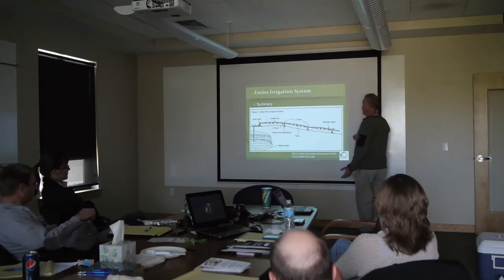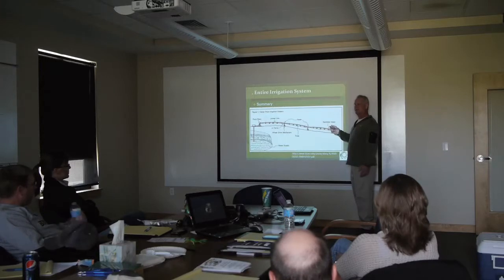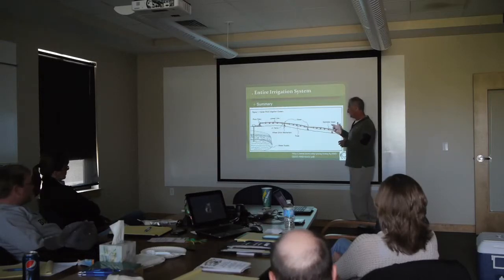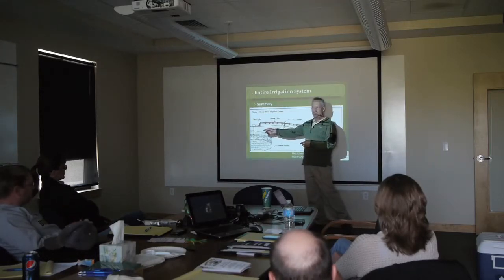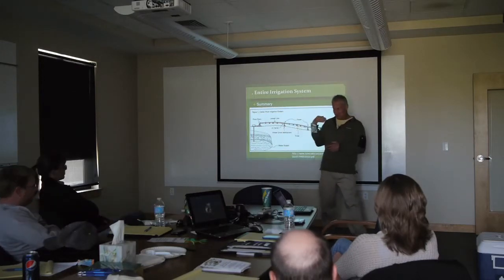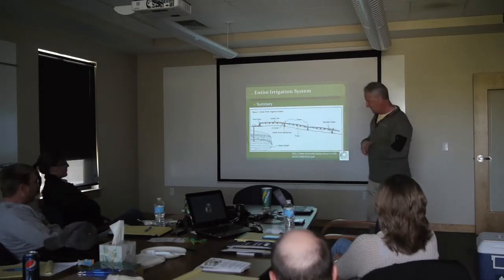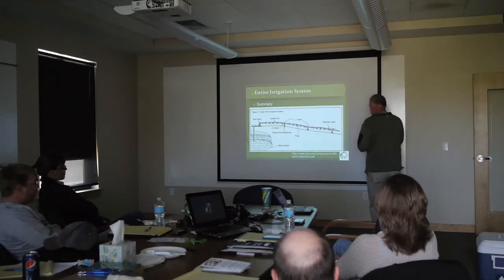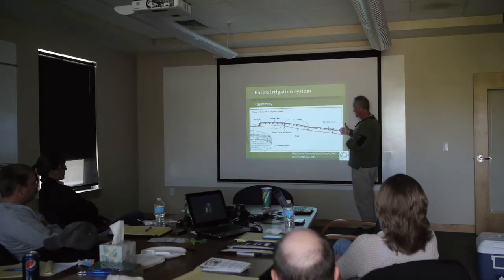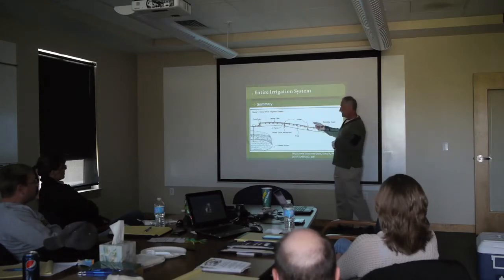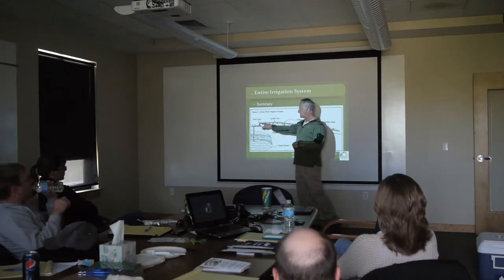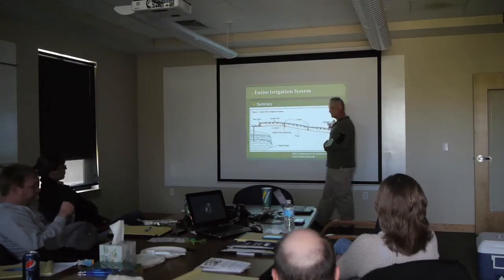But then, for each sprinkler, you say, this is how much volume is going through the sprinkler from the catalog. And so you have to add all those up, and that has to add up to the volume that the pump is putting out. The pressure, say 40 PSI here. You have to calculate all these pressure drops all the way. If the pipe is the same size, you can just say that much pipe, that size.